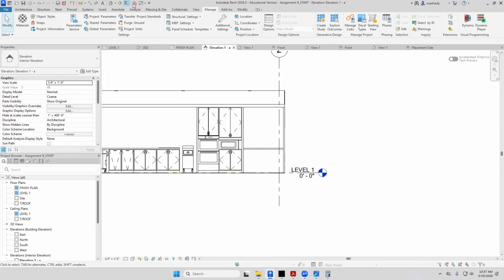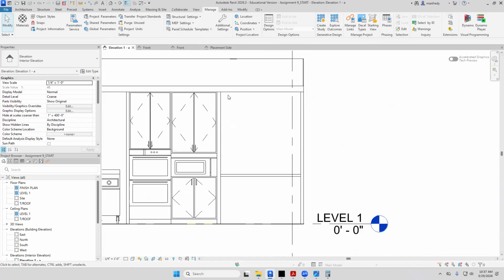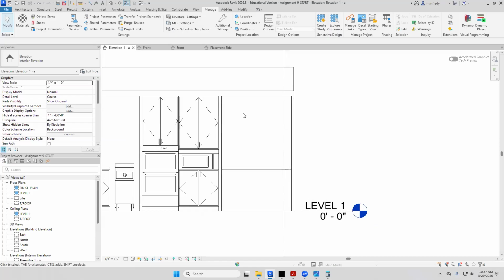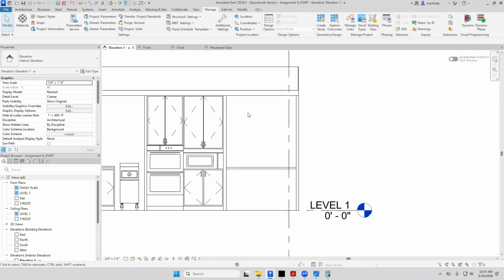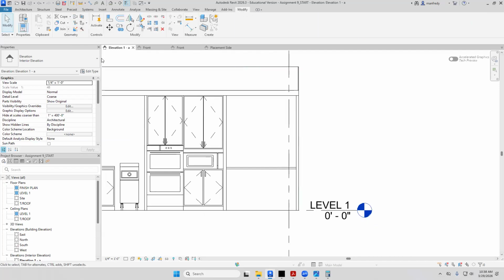So you have two options here. You either make a new wall and put it on top of this wall, make it 1/2 inch thick or whatever thick you want it, and give it a tile, or I can split face this and carve out an area right here and paint it tile. Both ways is fine. If I want to do it quickly, I'd probably go to here to modify and do a split face. This guy here.